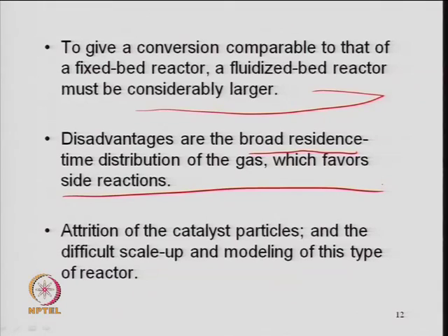So, in order to regenerate, you need a continuous recirculation of the catalyst, right. To regenerate the catalyst and send it back, or take a moving bed reactor, straight through transport reactor, which are now old type of reactors, but the new one is a reactor regenerator system for the fluid catalytic cracking, right. So, this is one issue here in the case of fluid bed reactor.